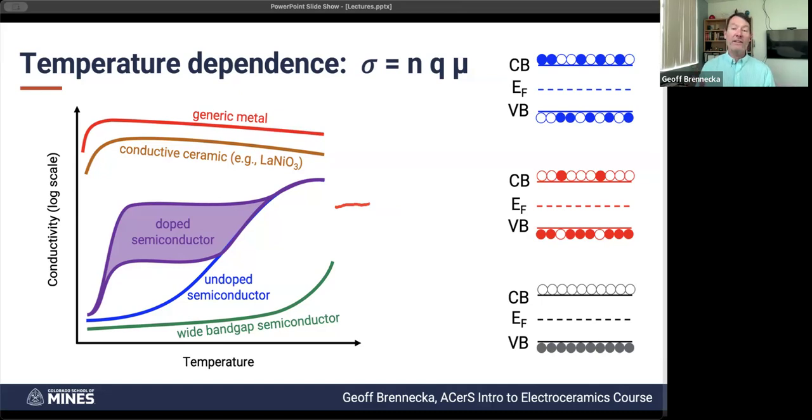electronic carriers. One example of this would be yttrium stabilized zirconia. It is a very good electronic insulator and a very high ionic conductor, but you have to get to a high enough temperature for those ions to move. So at low temperature, I'll draw it on the open section over here, you're going to have a little bit of electronic contribution, and then you're going to get to the point where the ions are able to move, and that's exaggerating a little bit.